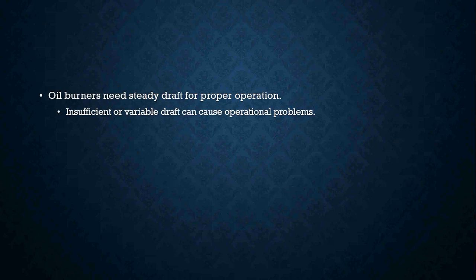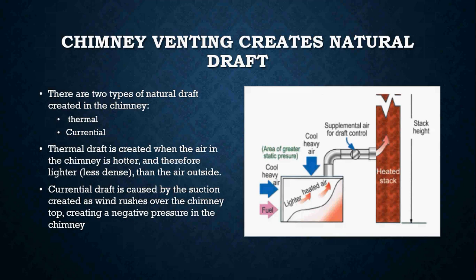So as a mechanic or install guy, whatever it is that you're going to do, you have to make sure that these units are operating at a good and efficient draft. Now, different manufacturers, different specifications. You have to follow whatever those manufacturer specifications are. You have to make sure that the chimney is constructed and sized correctly for that type of application. You can't just take a boiler and burner and slap it into a home and call it a day. You have to look at stuff in order for this to work properly. Otherwise, you're going to have problems.